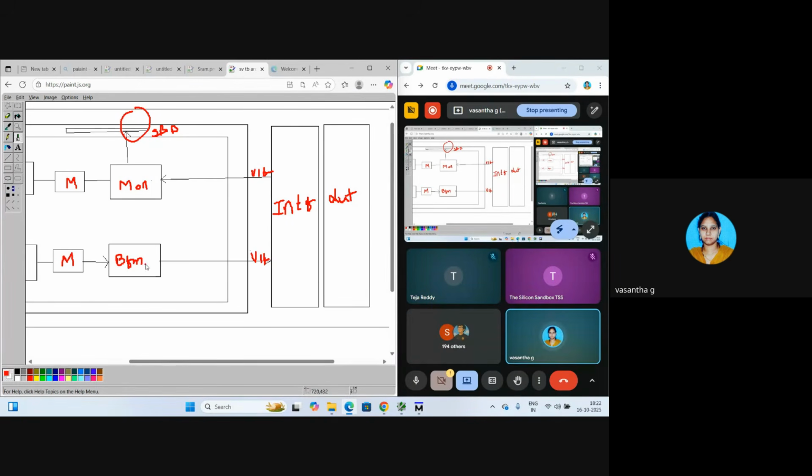So whatever we are driving, and the actual is what we get from the design that is already provided. For example, we have learned in Verilog, we apply the $random values to the A, B of the half adder. A, B are the inputs and you are passing the random inputs and generating the output. And after getting those values you are comparing with the truth table.